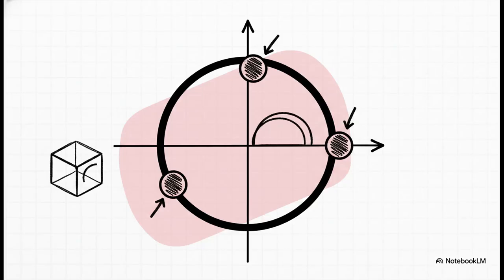Once you have the full circle drawn, you can read the results like a lie detector test for the material. The furthest point to the right where the circle crosses the horizontal axis? Yep, that's your maximum principal stress. The furthest point to the left, your minimum principal stress. The absolute highest peak at the top of the circle? That's your maximum shear stress. You literally just read the coordinates right off the graph.